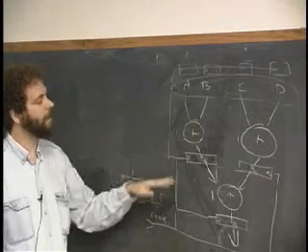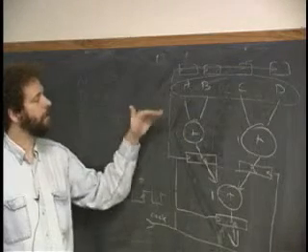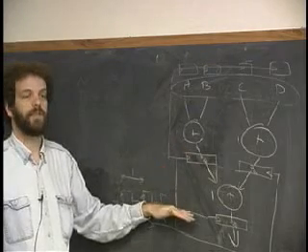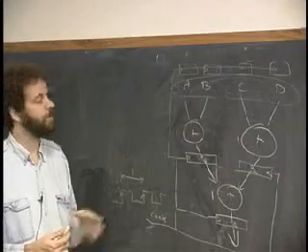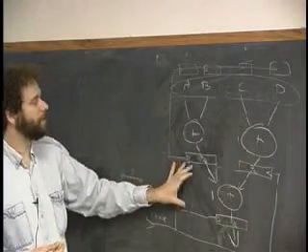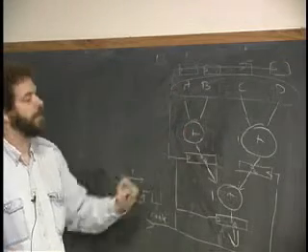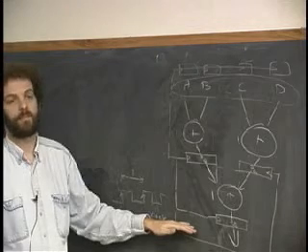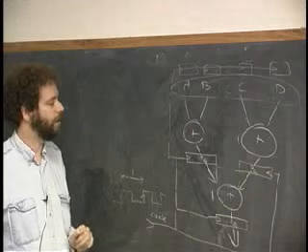In this case, the pipeline is perfectly balanced. What that means is that the time delay in this stage of 1 is the same as the time delay in this stage of 1. And so the latency doesn't get worse, because 2 times the maximum of the time delay between the stages is 2, right? That's the same as what the latency was before we pipelined the thing. There's no idling around in this circuit.